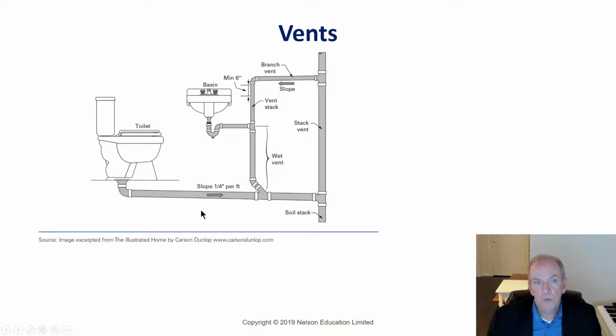So for example, right now I'm in Collingwood or wherever, and if I don't come up here for a long period of time, well, that water in the traps could evaporate out. In fact, it has. And then I've come up here and the place smells because there's sewer gas in the house, the methane gas from the sewers, and it's really not a nice smell. So the first thing I would run and do is fill the traps with water. All you do is turn on the sink a little bit, because this water will always stay up to this level, and the excess then goes down and away.